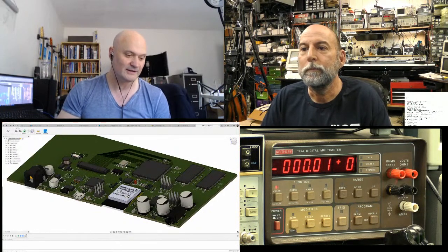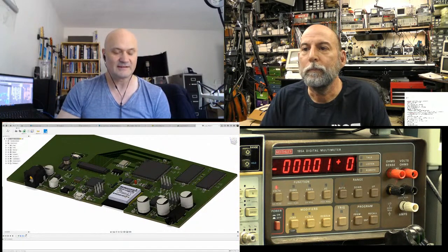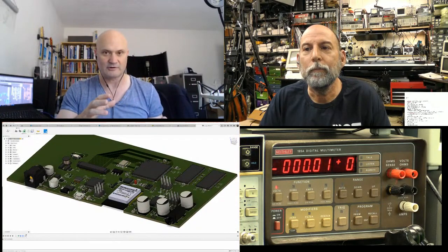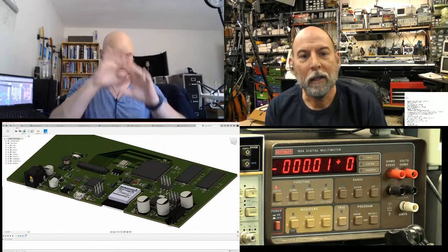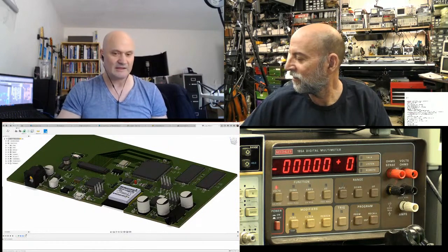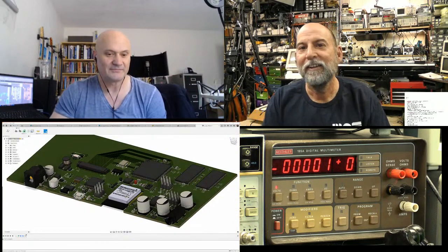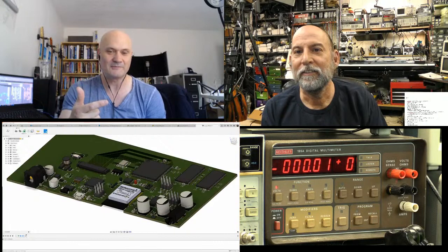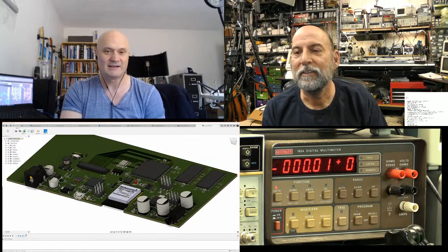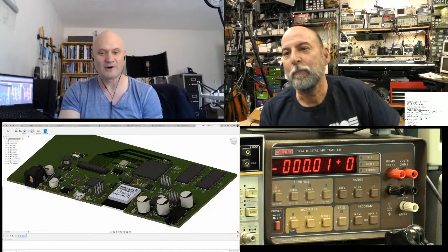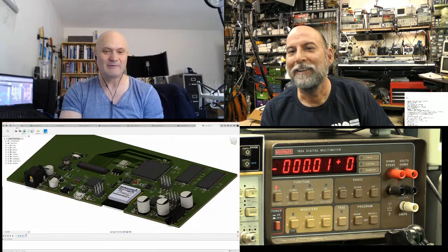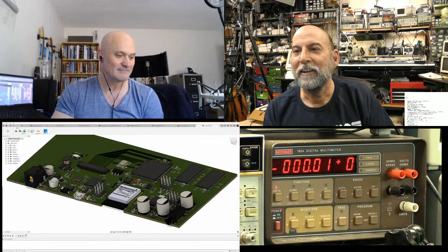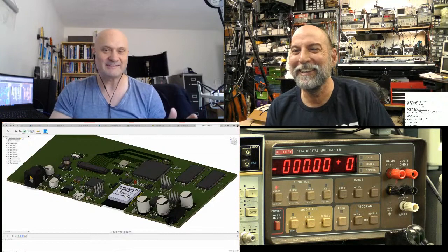And then later on, I thought, well, I'm going to want to. The purpose of this was to be like a smart 2D accelerated display controller that you could hook up any microcontroller to and issue serial commands over SPI to display stuff quickly. And then I started thinking, well, I might as well throw an ESP32 on there. I've got two cores with some DSP instructions, so I have some DSP acceleration there if I want it, and then I might as well throw on an audio codec. And now, before I know it, what I'm essentially designing here has turned into like a Commodore 64. A super advanced Game Boy, right?